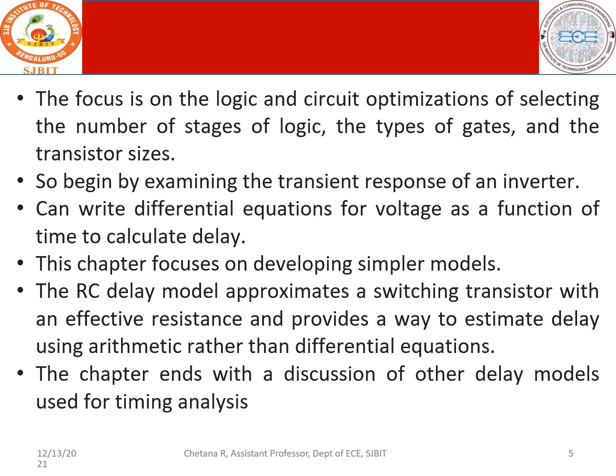This approximates a switching transistor with an effective resistance. Whenever you have an RC model, it requires the device to be replaced with a switching transistor with a resistance, and that helps us estimate the delay rather than using complicated differential equations. Of course, we should generally use the differential equations to calculate the delay, but that is more complicated, and therefore we go for the better model, which is the RC model, which helps us calculate the propagation delay in a much simpler way, and this is how it goes on in future.